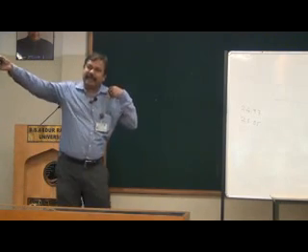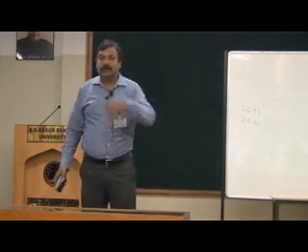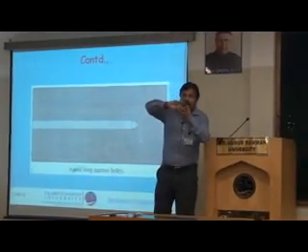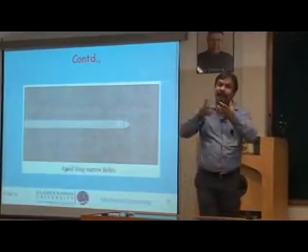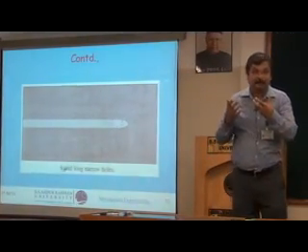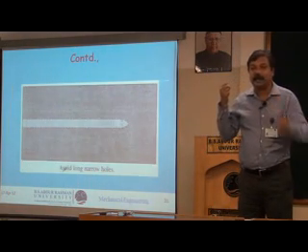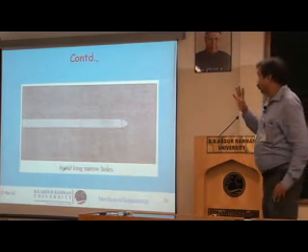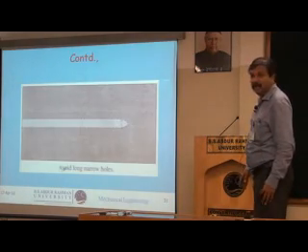When you make the cantilever very long, it may not be able to withstand the cutting forces and it may break. If it breaks inside, it is very difficult to take it out, because the drill bit would have tried to bite the metal and in that process it would have broken. It is very, very difficult to take it out. It's almost impossible. You may have to scrap. So, avoid long, narrow holes.